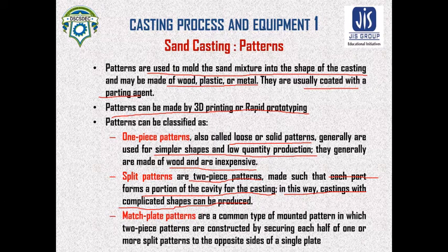And there is another type of pattern which is called match plate pattern. This is the common type of mounted pattern, in which two piece patterns are constructed by securing half of one or more split patterns to the opposite side of a single plate.